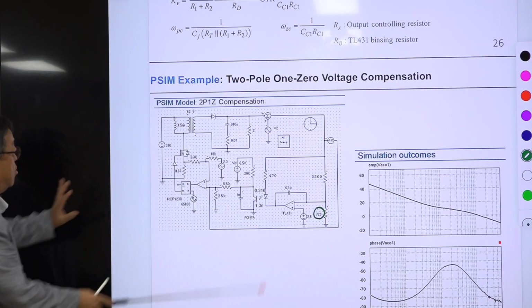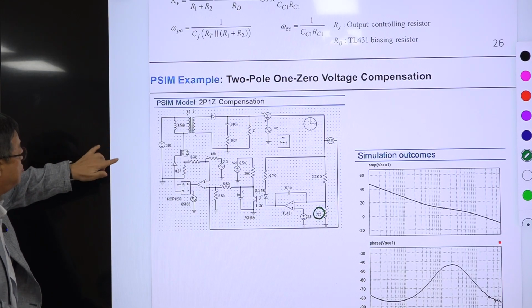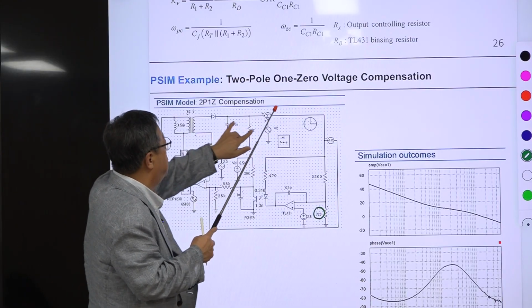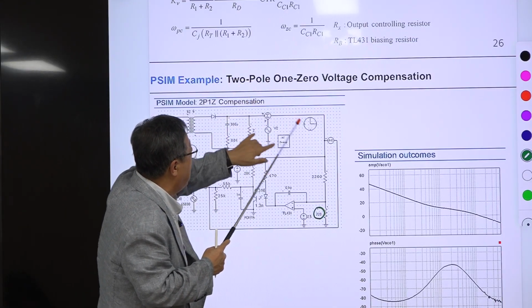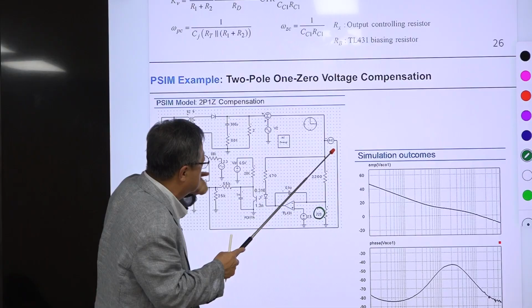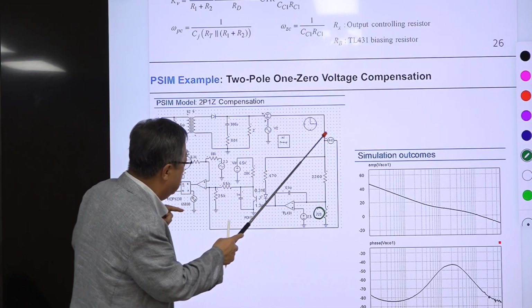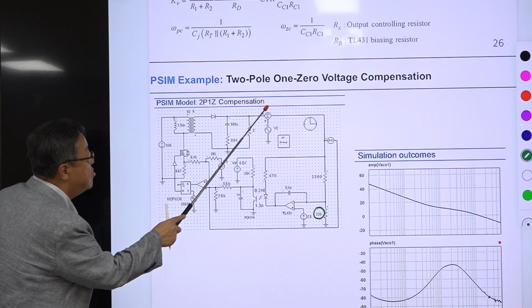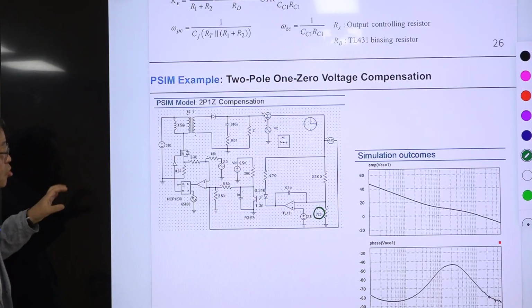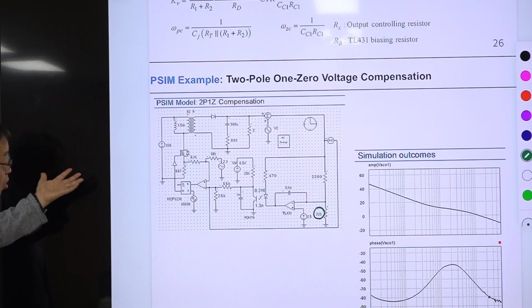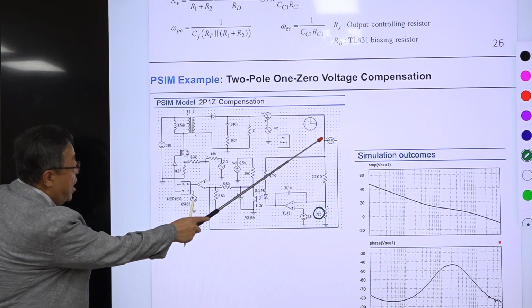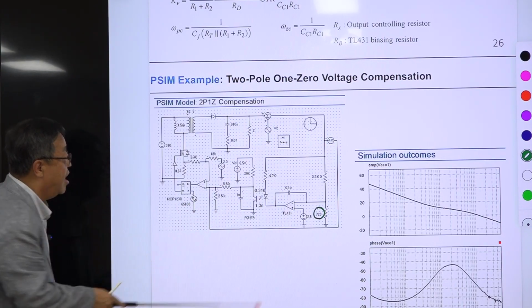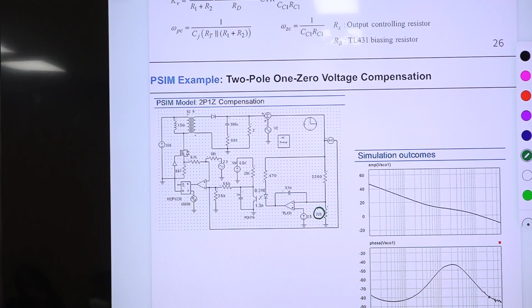So this scheme is very similar to the measurement of the loop gain, but this AC probe is connected here, right? Previously it was here. Then with that, we measure the control to output voltage with current loop closed, and if you connect here and here, then the denominator is dot. Terminal is denominator.